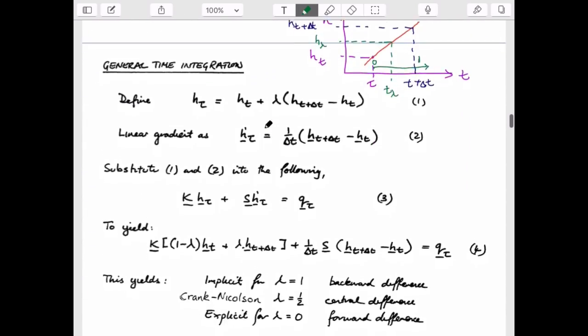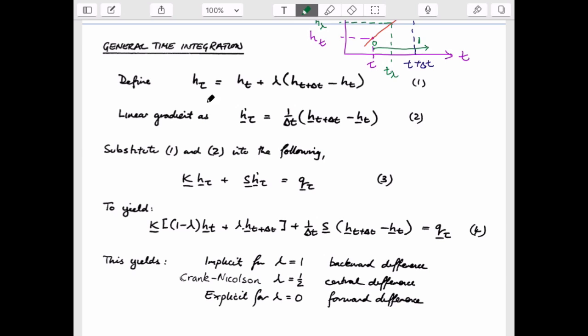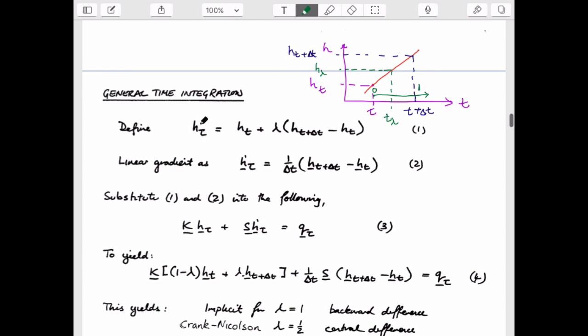Then we're really kind of writing a shape function. Actually, it's the term that we used to get the head at any particular location. So in other words, we can get the head at any particular location. Maybe I should call it h tau, because tau is the location we're choosing. And it's equal to head at the initial location, plus the difference between the heads, which is this amount here, this is delta H here, and this is delta H here, and all it is is the multiplier.